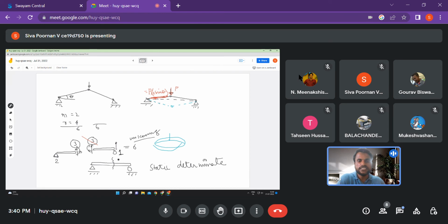Each part of the structure has to be in equilibrium, right? So we can apply three equilibrium equations in each of these two cases. But you need to be careful here actually. When we know that this roller cannot take any horizontal loads, this would become 0, and this would become 0, here also it will become 0. So you can actually do it for complicated examples. For other examples it will be quite simple to understand. So equilibrium equations will be 3 and 3.